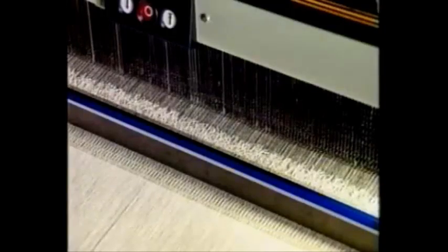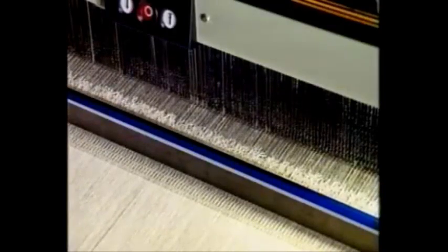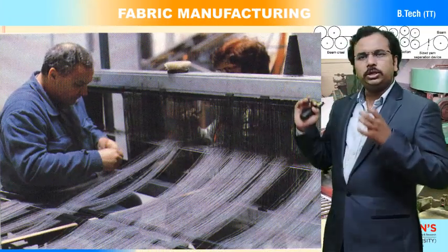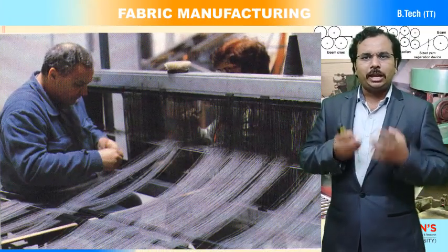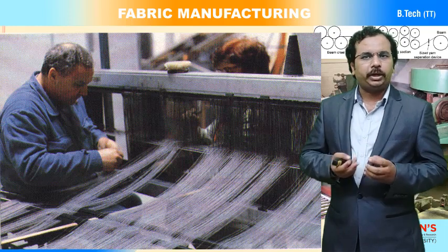If the new warp is going to produce the same fabric woven on the loom, the new warp ends can be knotted with the existing warp ends by a tying machine. Then the new warps are drawn through the droppers, heddle wires and the reed to start weaving. So the second person is going to use an element called a drawing pin.